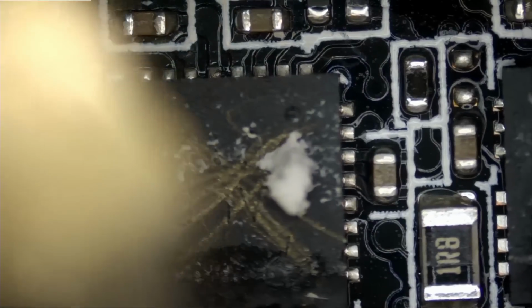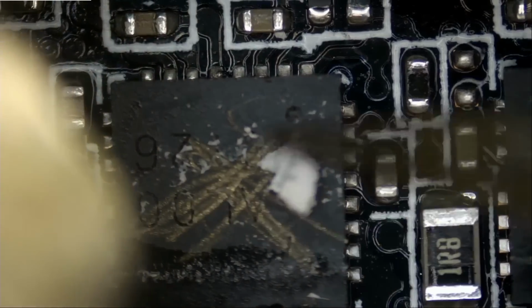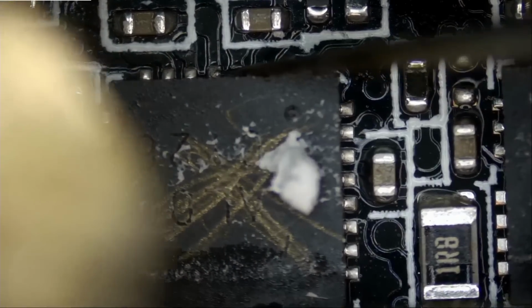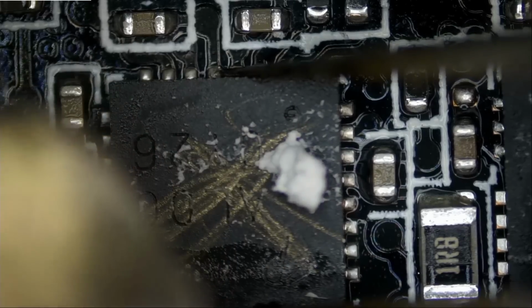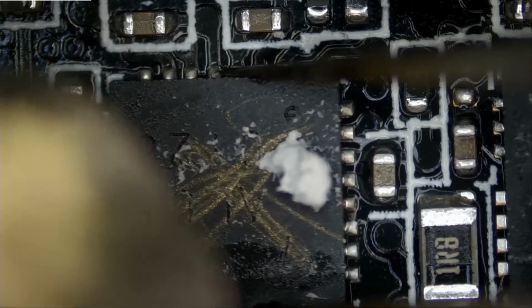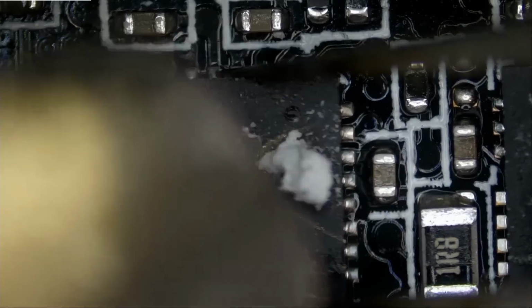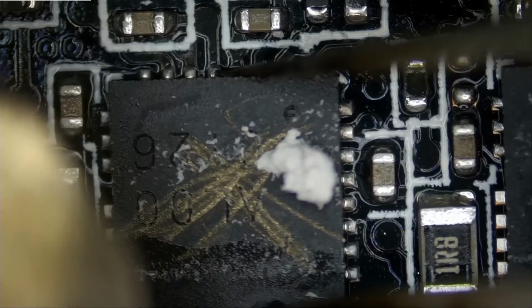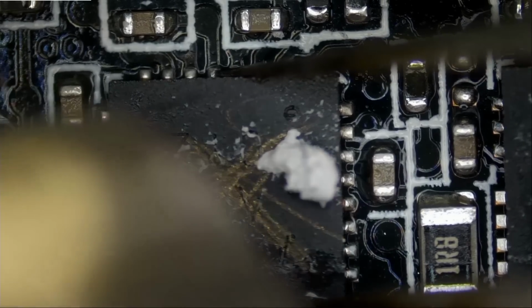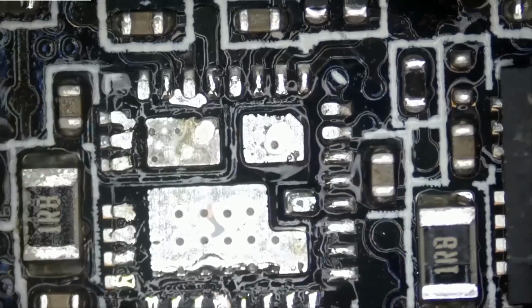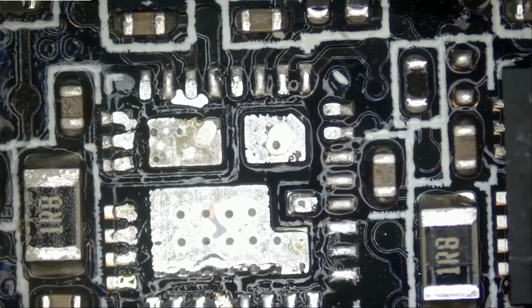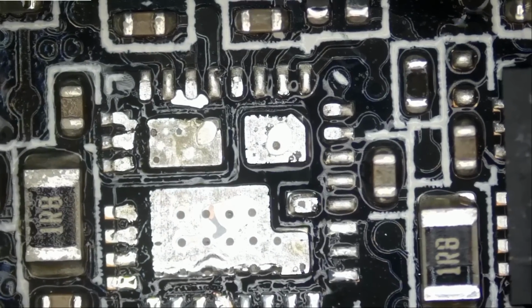The board is very thick. And the board is going to absorb a lot of the heat that we are putting on it right now. The board itself must reach the melting temperature of solder in order to be able to desolder this component. Like this. Great. Out.